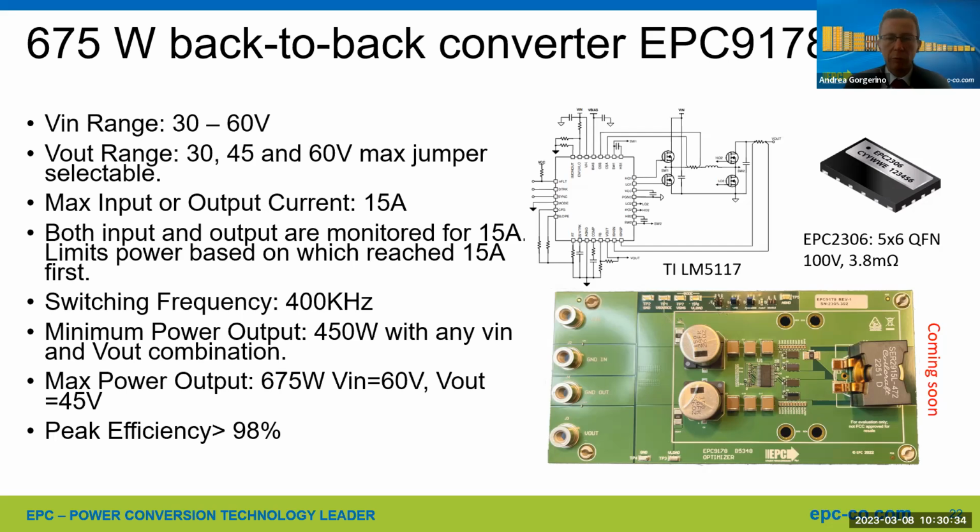Right now, we're switching at 400 kilohertz for this power level, and this is a 30 to 60 volts input and output back-to-back topology. Very interesting board for higher power battery applications. So this is coming soon. I think even probably within a month or so, we should be able to release it.